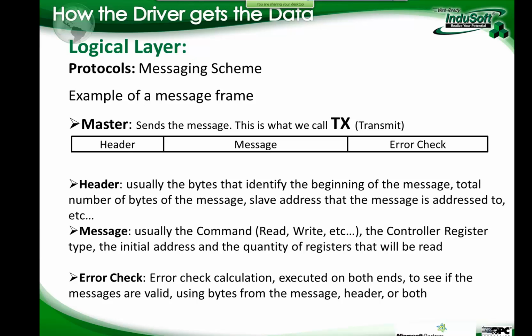Most of the drivers are based on the concept of having a header where you have, let's say, the station that you are going to communicate with, and the instruction that you are going to send to the PLC. Let's say I want to read; I have a specific function for that. On Modbus it's 03, read multiple registers. And then the message: if I'm writing, what value I'm writing to the PLC; if I'm reading, how many registers I want to read. And usually an error check at the end, where we take all those bytes that we sent and do an operation, usually an XOR among all the bytes, and generate a final byte or a final word of error check.